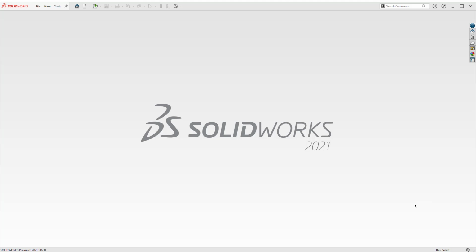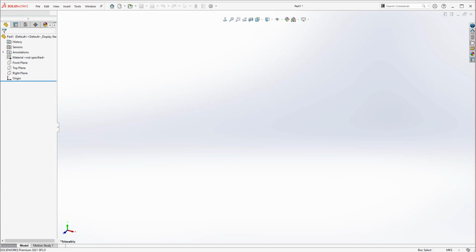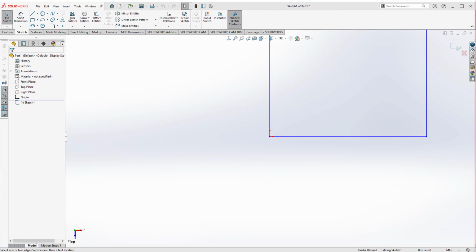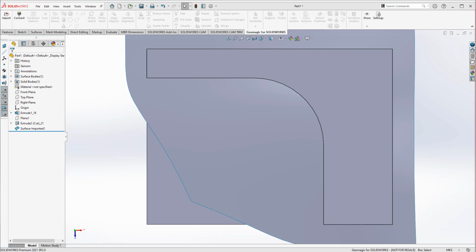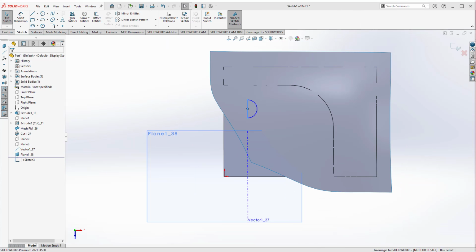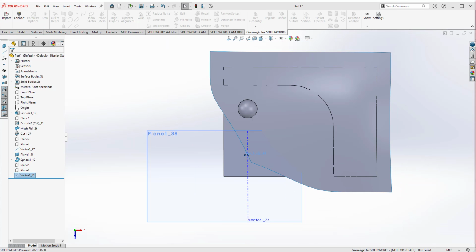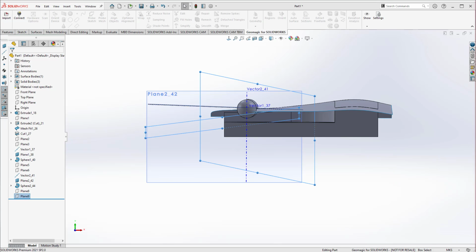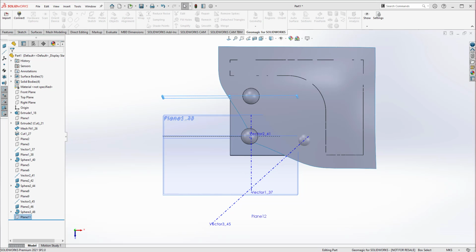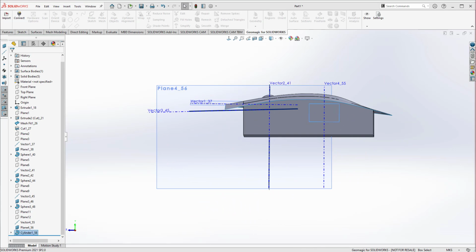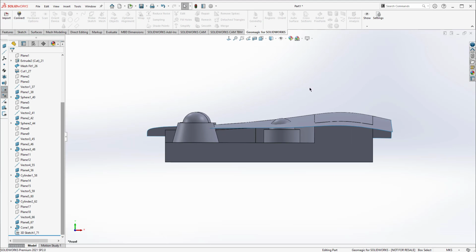So now you see the SolidWorks. Now if I go ahead and hit send, it'll open up a new part since I had no part open inside of SolidWorks. And it will build everything in here as native geometry inside of SolidWorks. So you see that mesh fit and all the features that I've modeled thus far will come across as native geometry. And once it finishes here, we'll have the ability to go back and make edits to that.